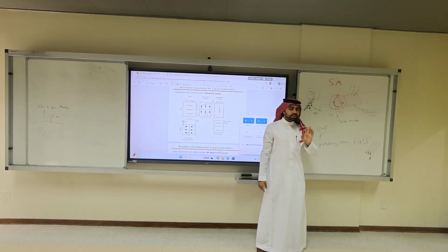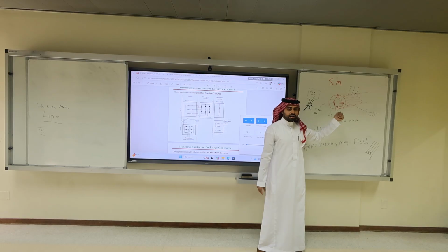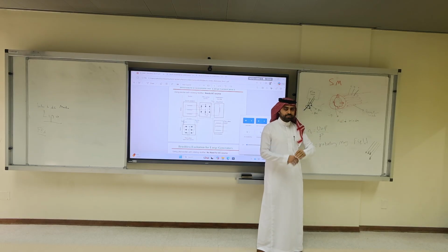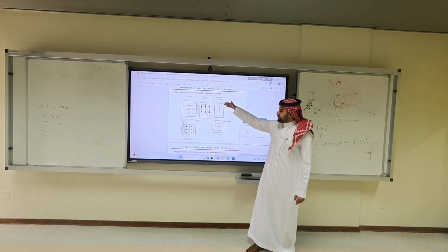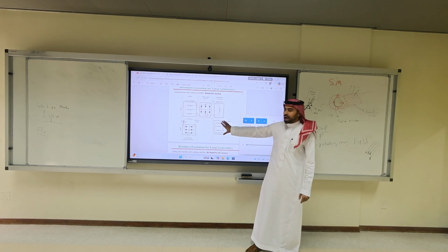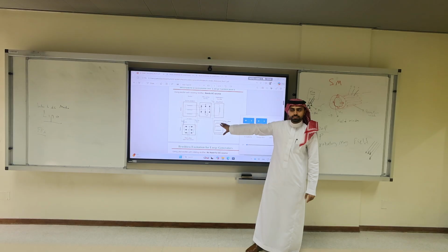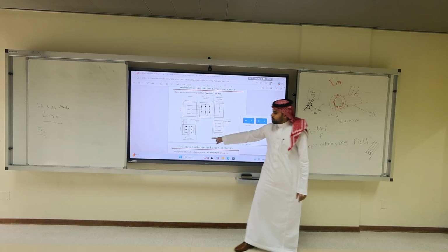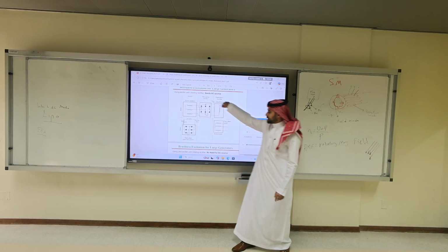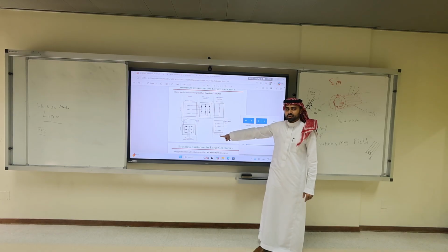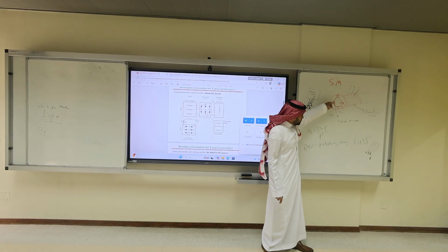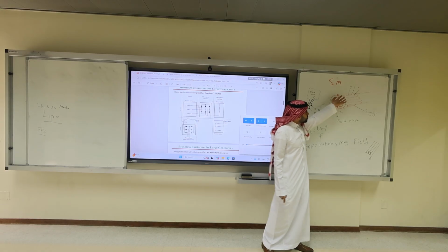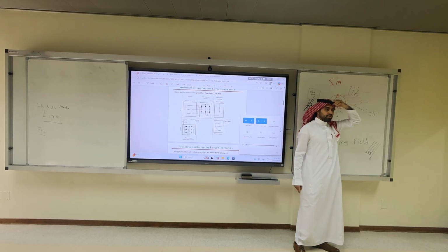This is not an induction machine. In an induction machine, the rotor has no windings except for a very small type. The synchronous machine, both of them have windings. Then apply that DC to the main winding and then you get your three-phase output, high power, high voltage. So we started with a small three-phase input, we got at the stator what? Three-phase output. Then you start moving the rotor, now it has DC, you get the ABC outside, the terminal voltage.